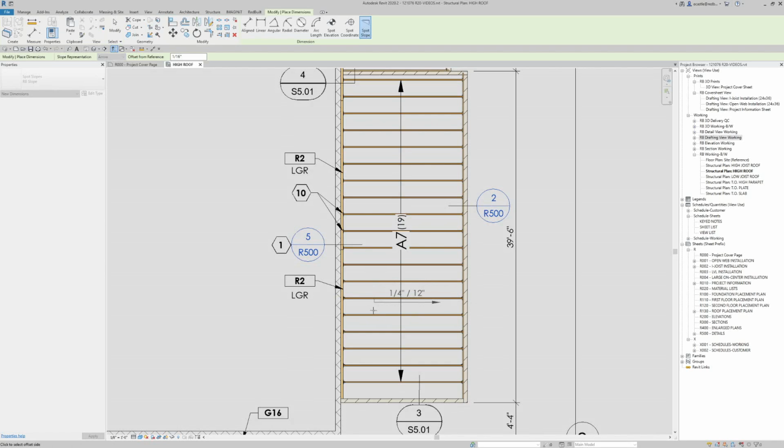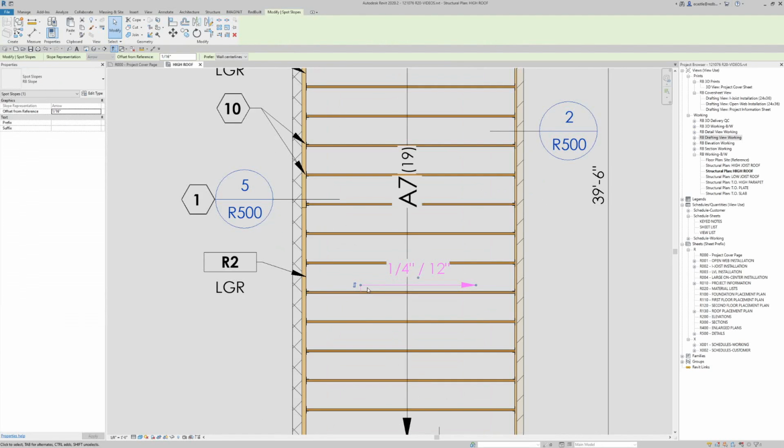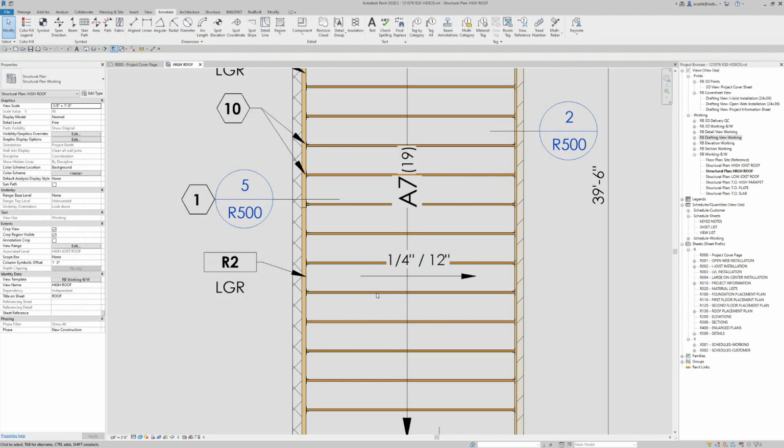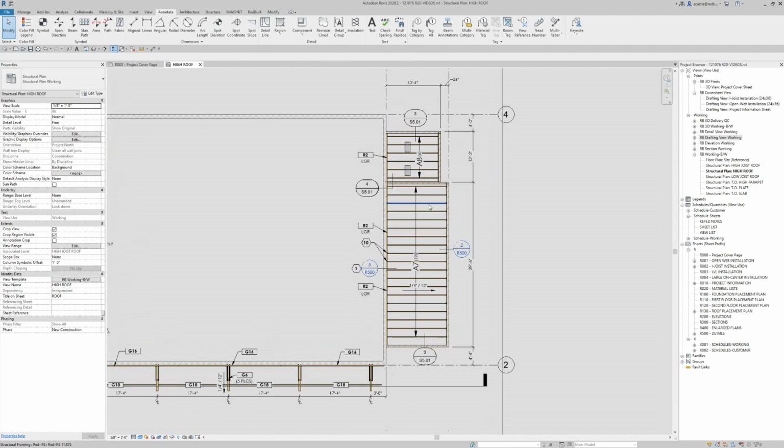And when you move it, you can put it on either side of the joist. Go ahead and cancel. A few options: you can use the grips to move the symbol, or you can flip the symbol as you need to make it visible and not covering up anything.